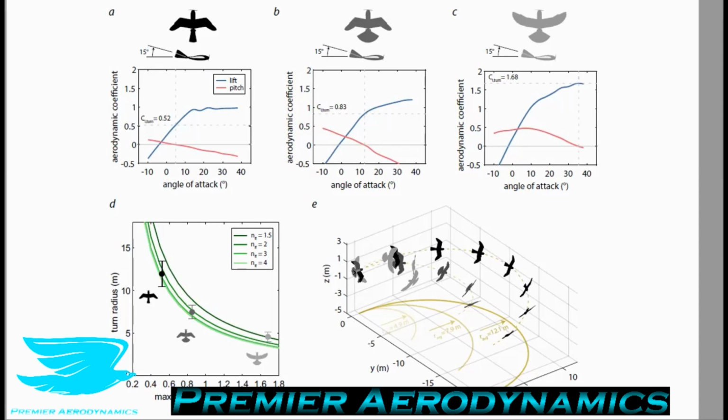While deflecting the tail upwards by 15 degrees for all these maneuvers. Deflecting it upwards by 15 degrees means you're producing a downwards force, and that's going to be pitching the nose up a little bit. During a steady banking turn, the drone is in equilibrium and the sum of all forces and moments is 0. Thus, it follows that the pitching moment coefficient must be 0 too. If it wasn't 0, you'd have an imbalance of forces and you wouldn't have a steady banking phase. It would be either accelerating into it or decelerating out of it. You can think of it that way.